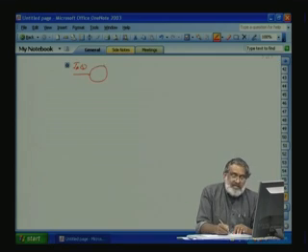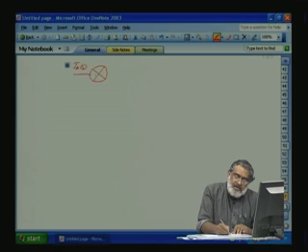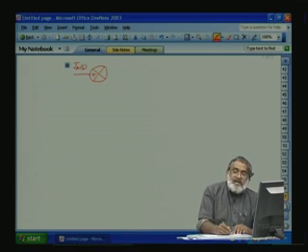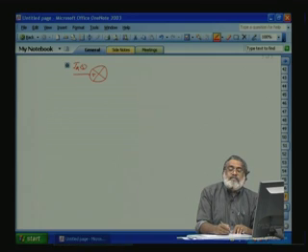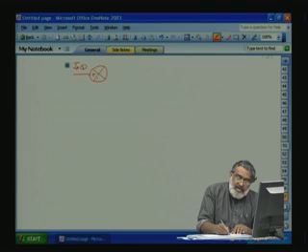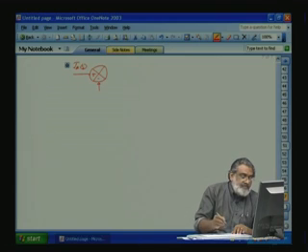From where this IAS reference comes, we will come to that. IAS reference is a reference current. We put this reference current so that there are maximum and minimum, positive and negative limits of this current, for positive torque and negative torque, depending on the machine rating. So there should be a current feedback from the machine.